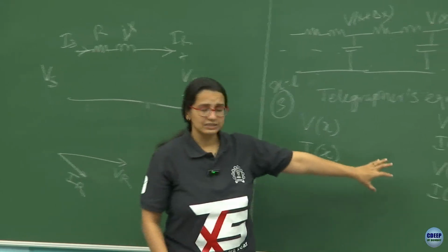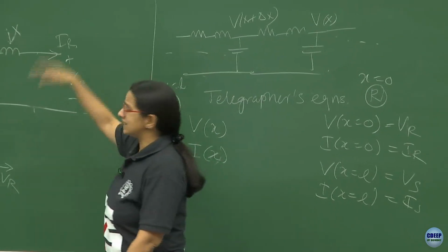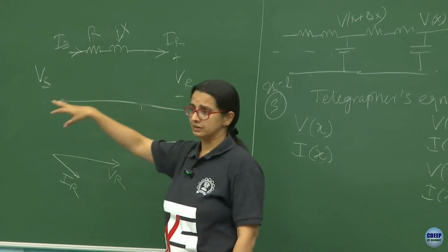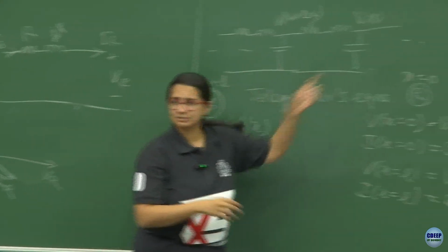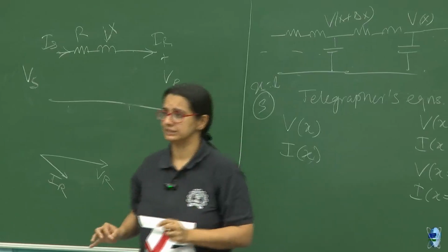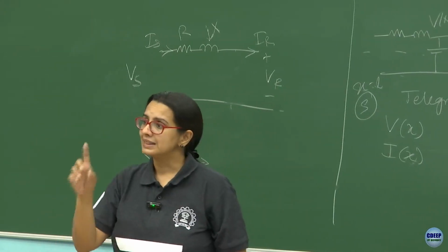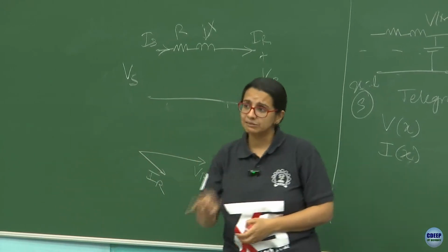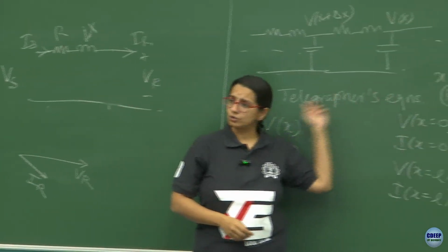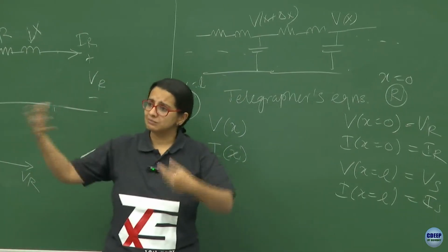Correct? That is what it is telling you. Now, if you were to construct equivalent circuits, so you ignore all of these blocks in between and try to come up with a model, a circuit in terms of R, L, and C components that gives you the same terminal relationships as what you would have otherwise gotten by solving these equations, then you come up with some interesting models.